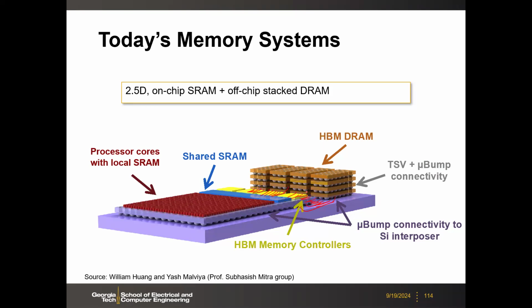Previously, if you recall, we talked about DDR DIMM. Every time you transfer how many? 64, right? Because the pin size is very large, you can visualize that, and then you insert that into your motherboard. So here, we have those wires connecting the DRAM to the processor through this silicon interposer.